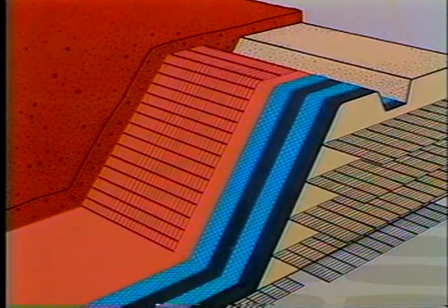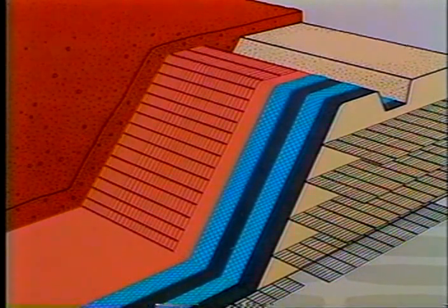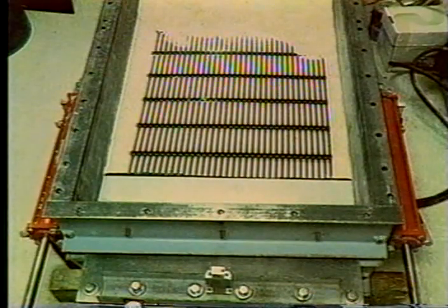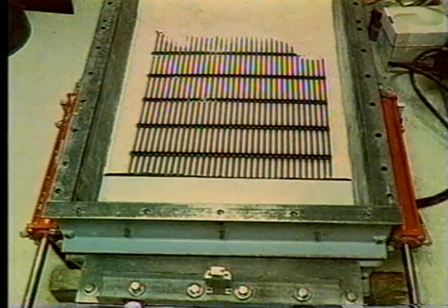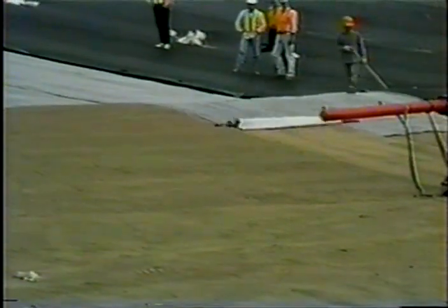To provide reinforcement, a geogrid must demonstrate good frictional properties at its interface with the soil veneer above it and the geotextile below. Interaction between tensile load and friction can be assessed by pull-out testing. We've seen that geosynthetic applications in landfills can be rationally designed and tested. However, their expected performance can never be achieved without proper installation and quality assurance.